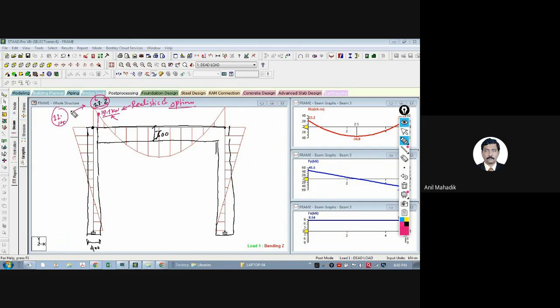That's it. So that's why for steel structures we generally use Staad Pro, because in steel everything is modeled on center lines, we don't take results at the face, we give slightly higher, because there are connections and other things. So every software is important for different types of structures.